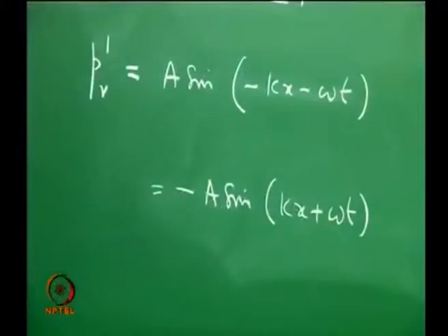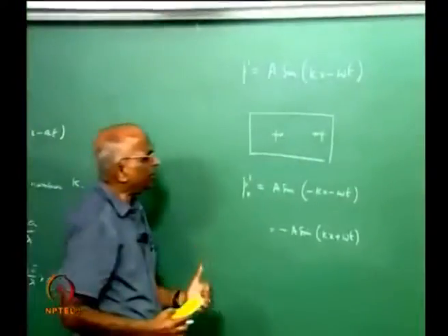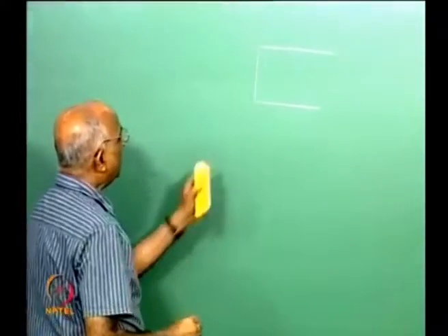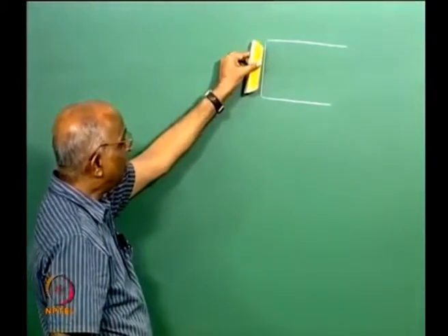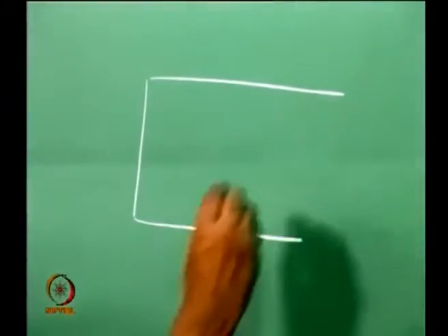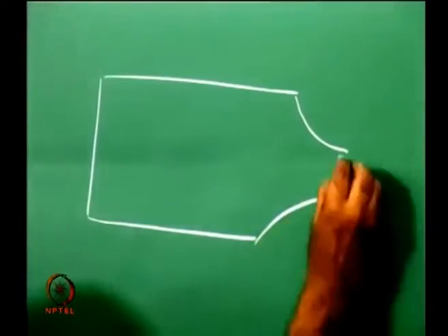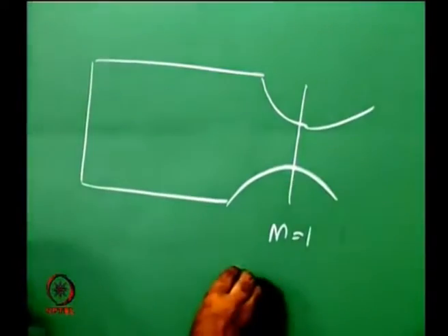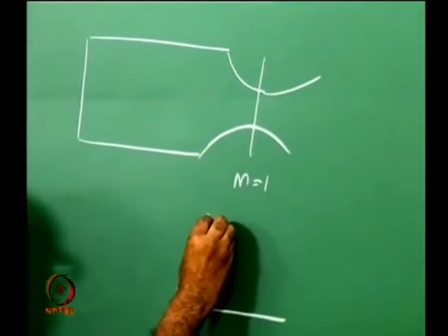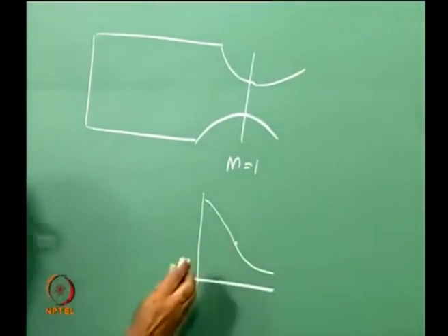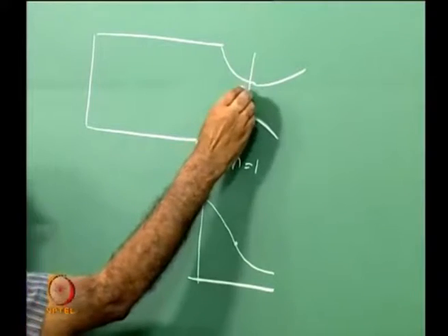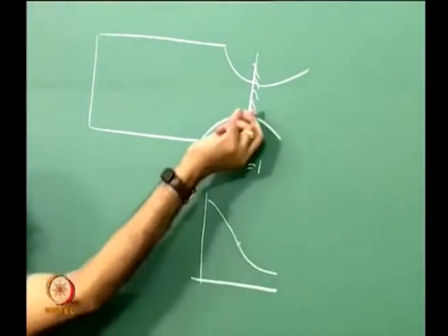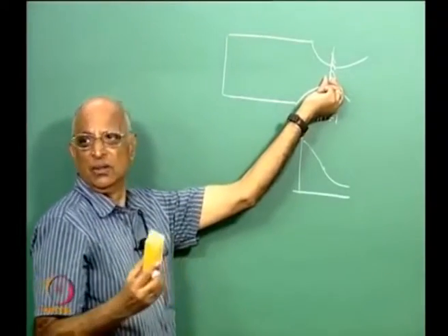Now, we want to find out, see, after all, for a rocket chamber, we have been repeatedly telling that a chamber consists of something like a hole, a cavity, and what does the cavity consist of? Here it is blocked, here you have the injector, nothing can go in this direction, and you have the nozzle in which high velocity gases are flowing, the throat is sonic, Mach is equal to 1, and whenever we plotted the density variations and pressure variations in the nozzle, we found that the density keeps decreasing, it becomes very rapid at the throat, and therefore, there is a very rapid change in density at the throat, therefore, this is as good as a solid surface. There are so many changes taking place in the throat region that it behaves something like a solid surface itself.